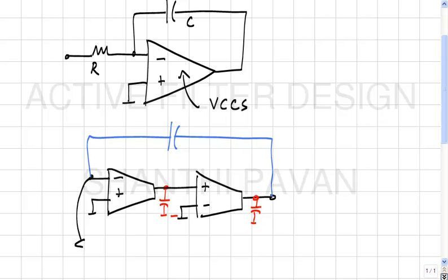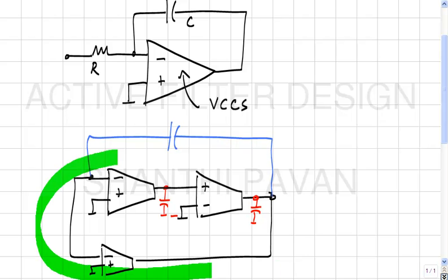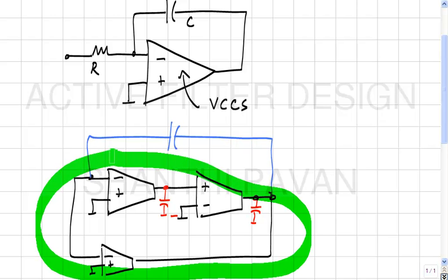So what we said is that it is indeed possible to hook a resistor here, but implement this as a transconductor this way, right, and then we see that putting it here or here does not make any difference, right. And if you now look at this contraption, it is now a transconductor